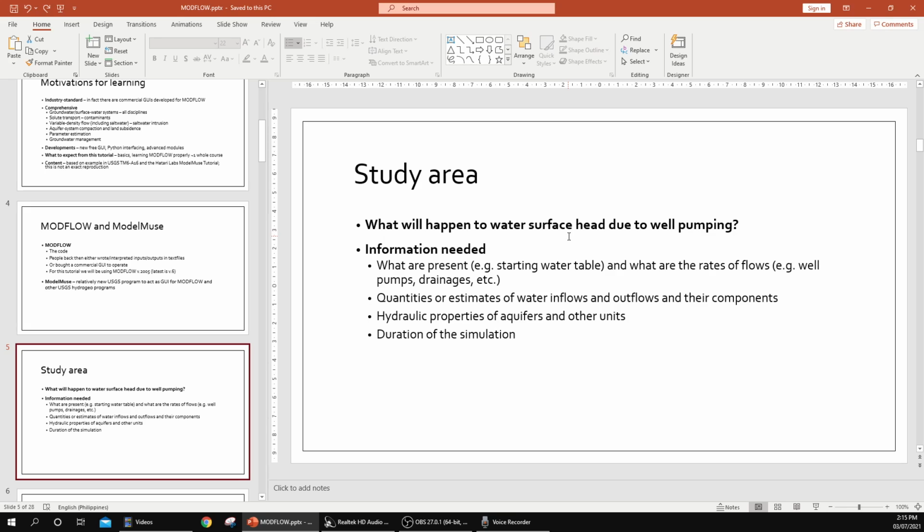All right, when you're talking about hydraulic head, if you're dealing with unconfined aquifers, the hydraulic head is just equal to the water table. But if you're talking about confined aquifers, the hydraulic head is not equal to the water table, but it's equal to the piezometric level, or the potential level of the water, right?